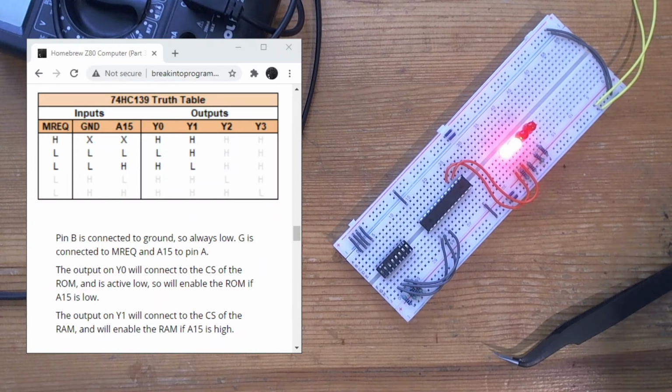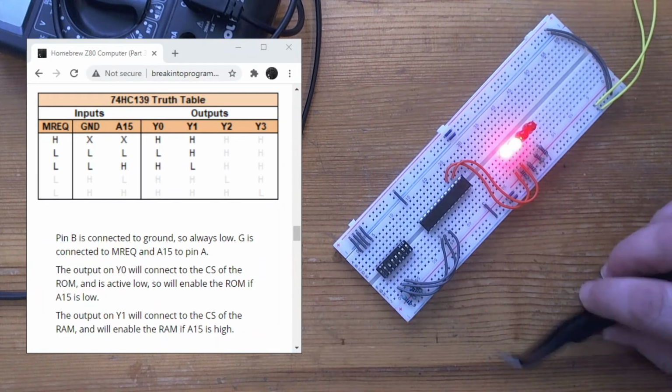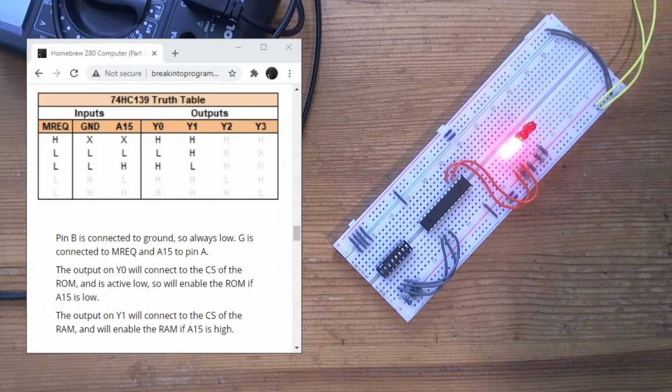Thankfully, a software update and a firmware update fixed that. I am now running XG Pro version 10.3.1, which helpfully updated the firmware on my programmer to version 4.2.118, and that seems to have done the trick. I can now program the device correctly, and if I read or verify it, I can see the contents with no issues whatsoever. So let's check whether or not my logic works.